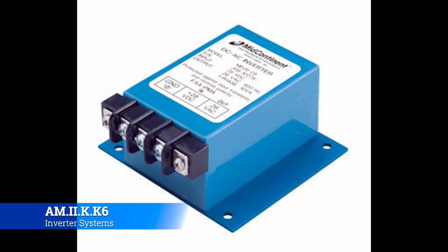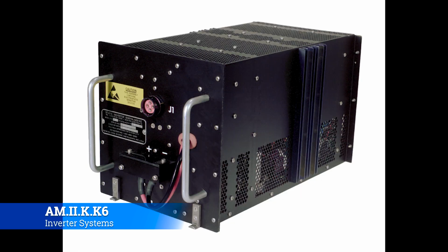And so you'll see these types of systems far and wide, and especially more and more as the future goes on. Now, when you get to the 737s, your bigger heavy commercial aircraft, this is what they look like. They're huge. There's actually an airworthiness directive that went out not too long ago about these overheating. They're just getting older, they get dust in them, and then they get hot and they'll burn up, and they could potentially cause a fire. But that's what an inverter looks like. They'll call this a static inverter on a heavy commercial aircraft.